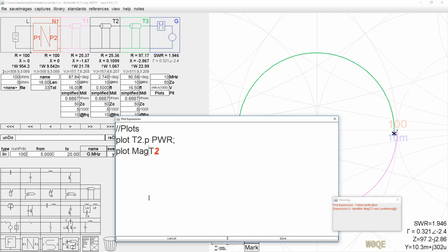I'm going to have to call this magnitude in this case, because the voltage that I want to look at, capital V, is the voltage I want from here to here. I don't want to know the voltage across the transmission line from end to end. I want to know it across the line. This is a complex number, this V, and I can't really plot that. I want the magnitude of it. So I'm going to plot T2.V, and I'm going to plot it on a graph that I'm going to label volt, let's just say, and I'm going to use axes Y1.